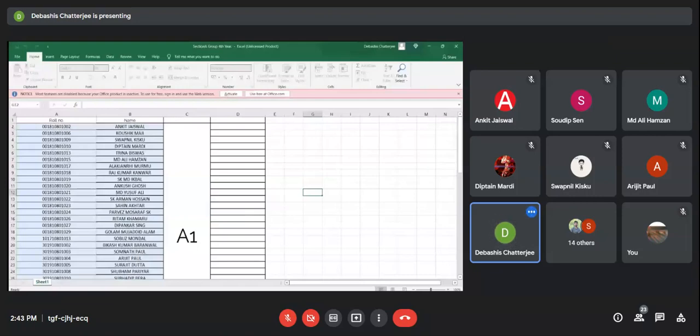And temperature rise 40 degrees centigrade above ambient. So ambient, in India it is 40 degree average ambient. You can say that 40 degree. So 40 degree or 45 degree is above 40 degree ambient. In the other problems, I will not indicate what is the ambient temperature, so you can take 40 degree as ambient universally. Normally 25 degree is taken, but in the current scenario, I think it is better to design for a little bit higher temperature.